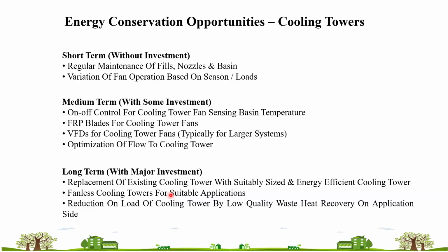Okay, so if the capacity is 400, 500 TR or more, then a fanless cooling tower should not be recommended, right? Yes, because the size will be very big and practically it may not be possible. The sizes go on the higher side. The entire civil and mechanical dimensions go on the higher side. Yeah, correct. Okay, sir.